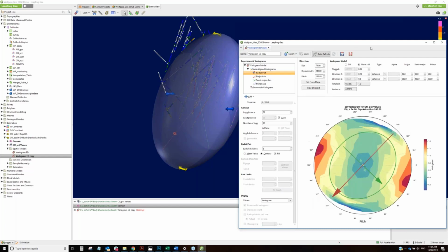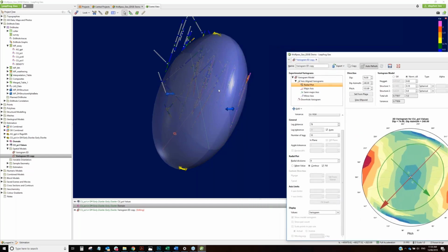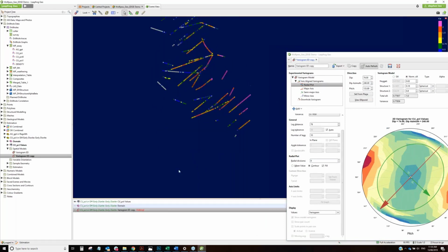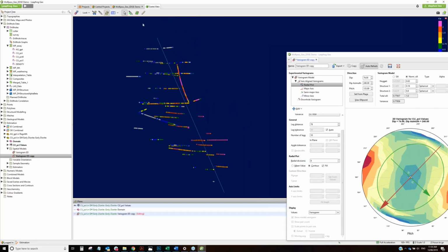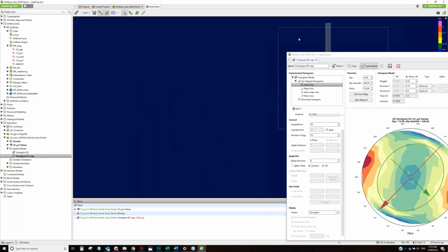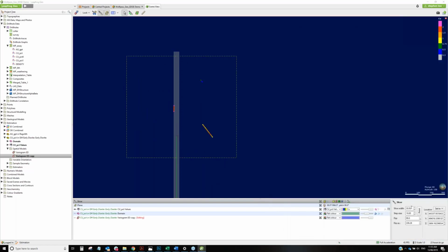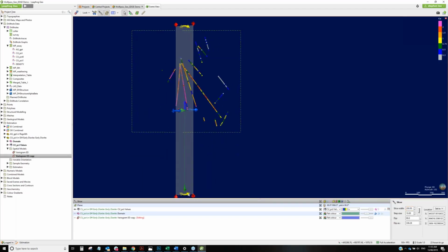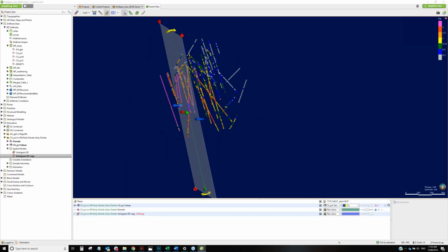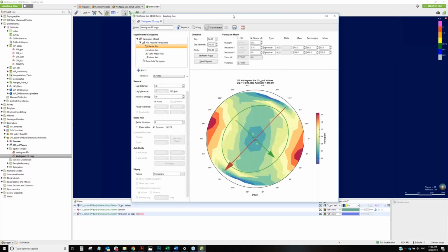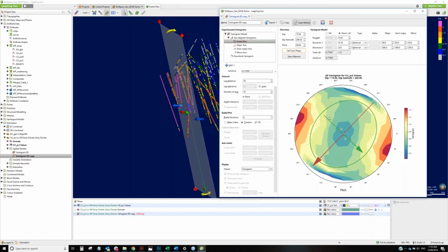In terms of the radial plot, often what we can do as a starting point is, if we're looking at this data and we think that the plane of continuity is running down through that way, that's the strike. Have a look in dip. Let's open that out. And just for the sake of it, maybe the dip's this way. We can set a plane, and then back in here we can go set from plane. Whatever the last plane was in the 3D scene, we can set that, and this will change.